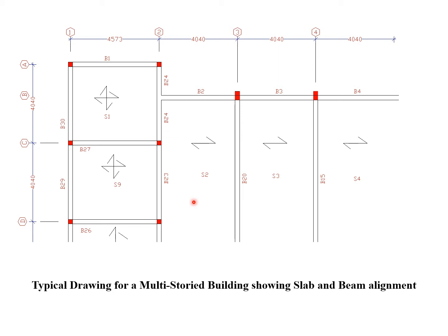To reduce the depth, we are supposed to insert one column at regular intervals. This is how the spanning of my beams, spanning of my slabs and location of my columns will be decided. So let us see a video tutorial which talks about how to plot